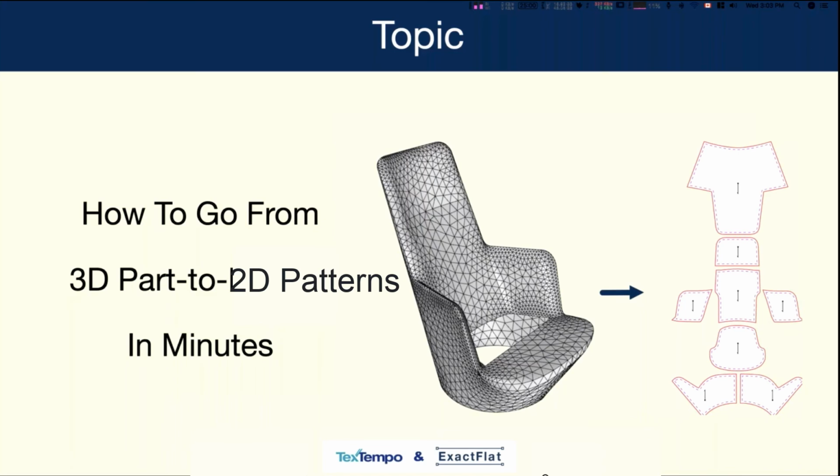As we do our flattening, we're striving to minimize the average energy density. We want it so the pattern piece that we generate after flattening, you won't have to stretch it in any way to get it to fit onto the 3D shape. Similarly, we don't want any excess sag, so we don't want visual wrinkles or folds or fingers of material on the pattern piece.